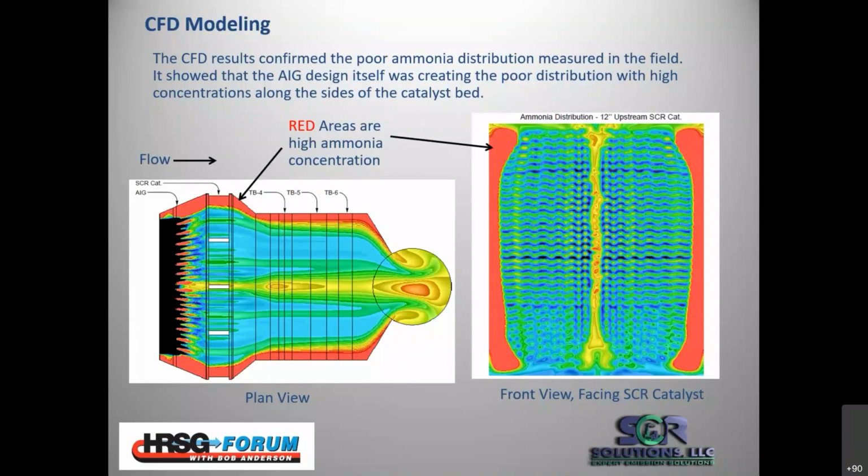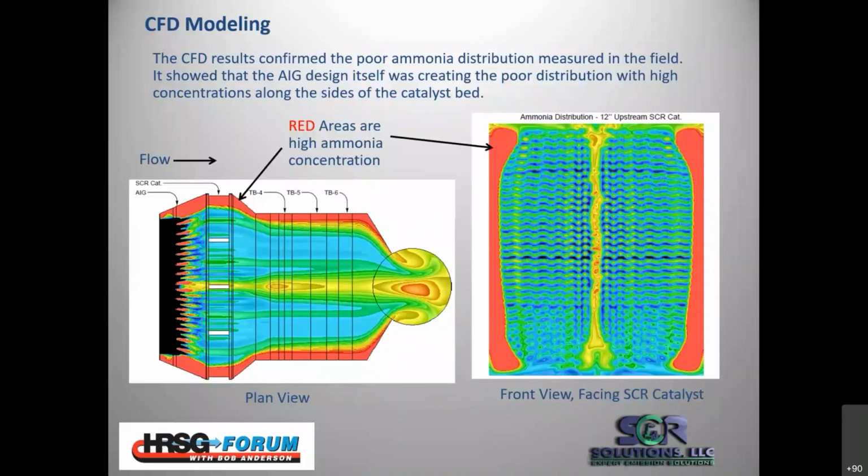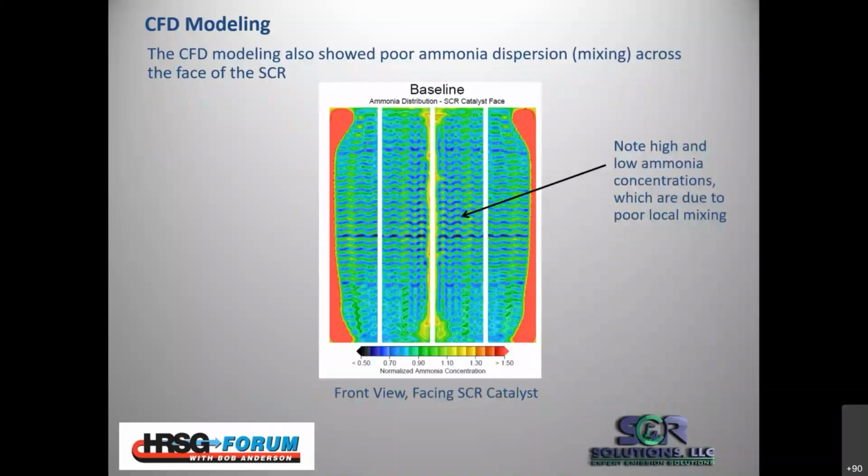And the sidewalls. So, that heavy ammonium bisulfate buildup on the tubes was really concentrated in these high ammonia slip areas. And again, there was nothing we could do with tuning to take it away. The AIG did come in from both sides of the HRSG, which was good, but there was no way to fix it unless you start blocking holes, and the AIG, which we tried with the CFD, was considered ineffective. So there you can see the distribution along the sides.